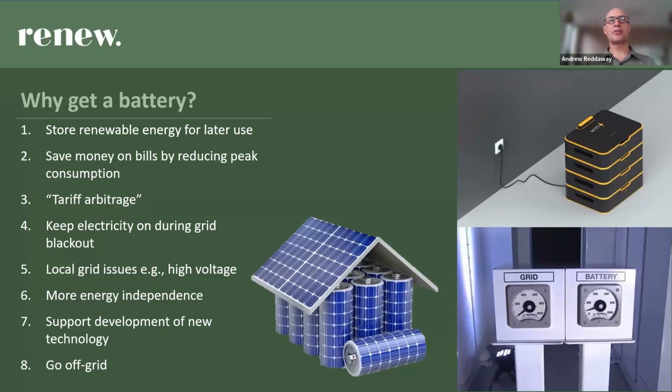If you're in the suburbs and you have an existing grid connection and you want to sever it, then really it's unlikely to be economic because you need lots of solar panels, you need big batteries, and you probably need a backup diesel or petrol generator as well. On a sunny day, you'll be fine. Your batteries will be full by midday, but that's not the issue. The issue is when you have a whole week of cloudy, cold weather, you're hardly getting anything from your panels. So how do you cover that if you sever that connection?